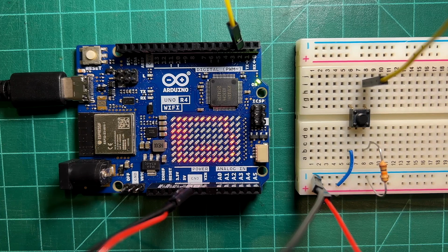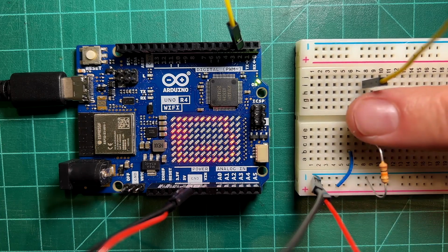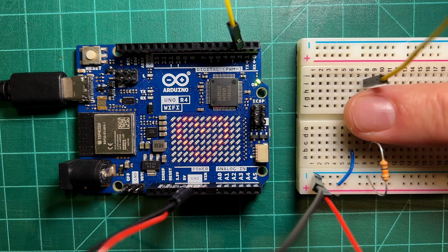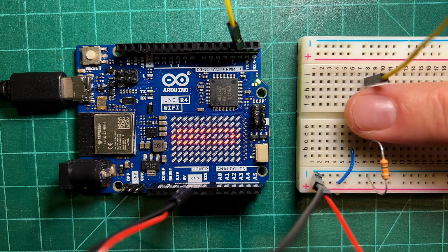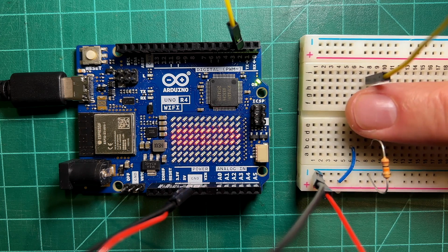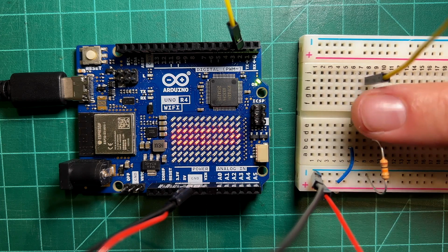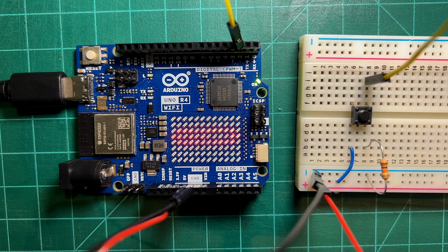Before we get into coding, let's discuss how our circuit will work. We will have a single button on a breadboard. When someone presses it, we want to change the frame that is displayed on our LED matrix. So in our program, we want to capture the moment the button has been pressed. Once pressed, that is when we will execute additional code to update the frame. To do this, we are going to track and read the current and previous value of the button with each iteration of the loop. We can compare the values to detect when the button is pressed.